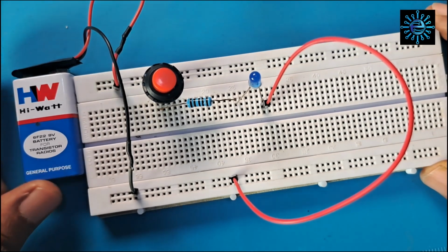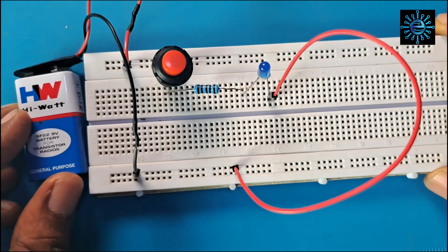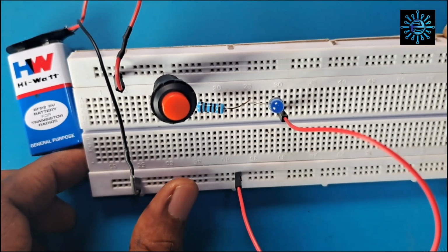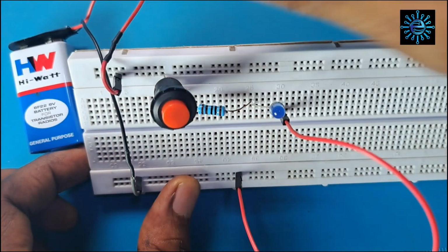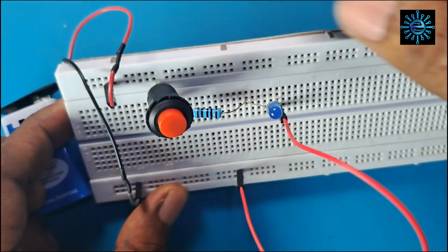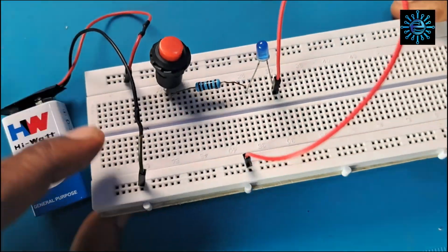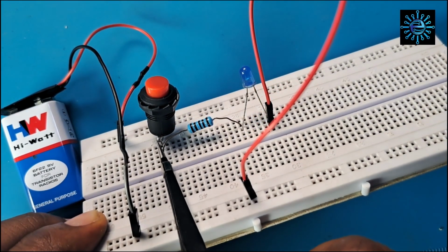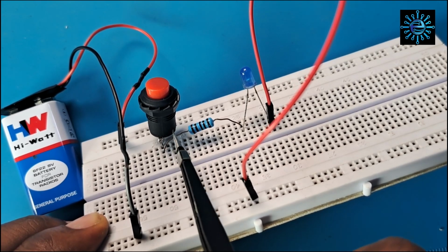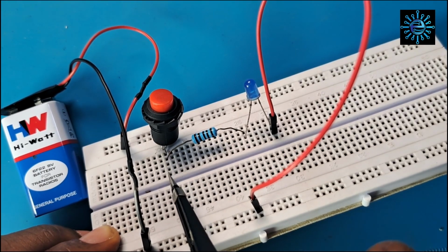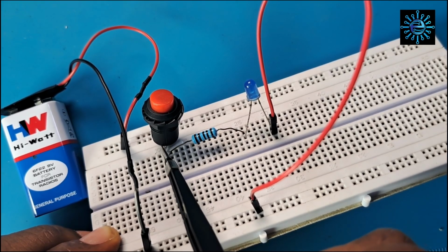On our circuit, we have the battery connected to the switch with the help of a battery cap. So the positive leg of the battery, which is this red wire, is connected to one leg of the switch, and the other leg of the switch, the second leg, is connected to one leg of the resistor, and the two of them are connected on this line of the breadboard. Anything connected on this line will make contact with these two legs of these two components.